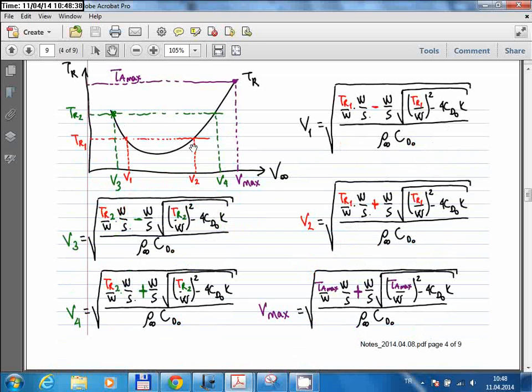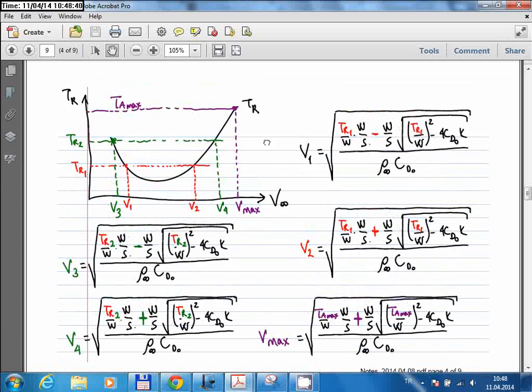So from this curve we can already find the maximum speed of an aircraft. So the maximum speed will be achieved when the engines are producing the maximum possible thrust. And for example, if the maximum thrust value is this much, then this is the maximum flight speed of your aircraft, maximum cruising flight. So you should be careful about that. So remember, this curve is for steady level flight only, and the maximum steady level flight speed is then found by using the maximum engine thrust.